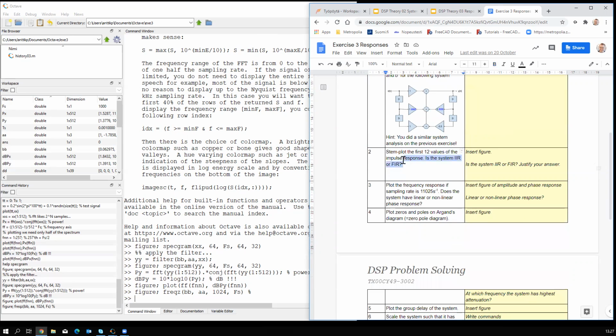So you can make an impulse response of the system, define it as infinite impulse response or FIR. As I said to you, the flow chart does not guarantee anything. So even if there is a feedback, it's not a guarantee that the system is infinite impulse response.